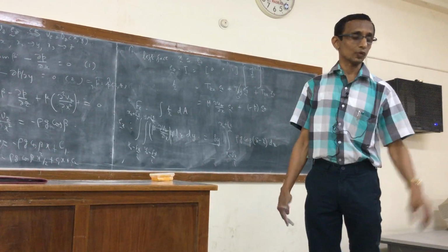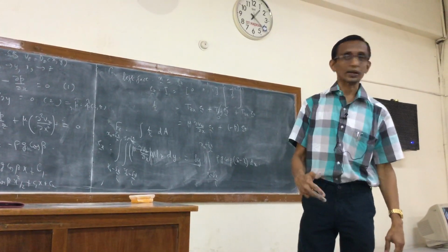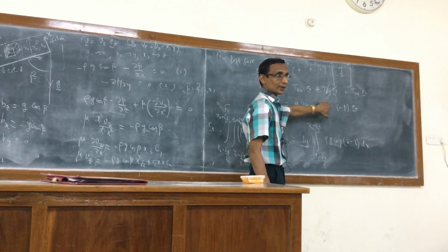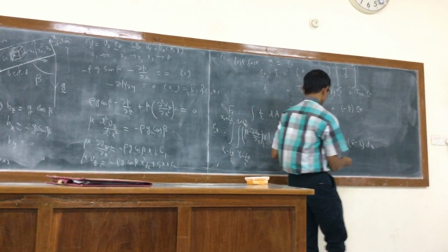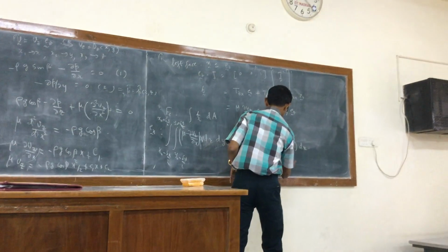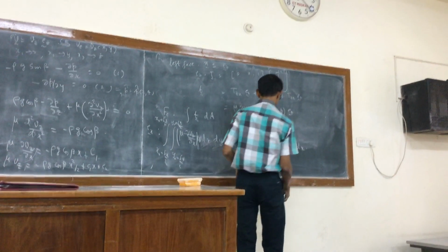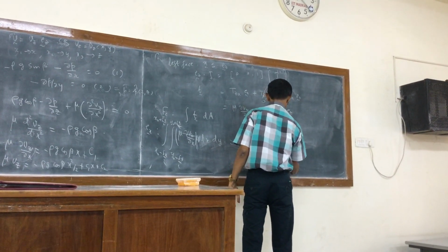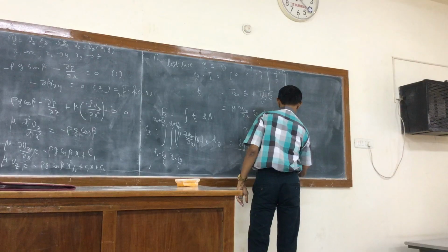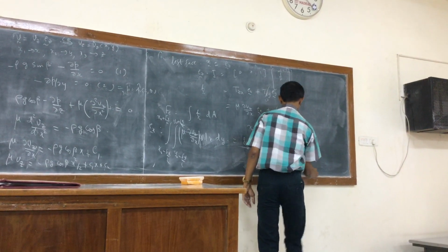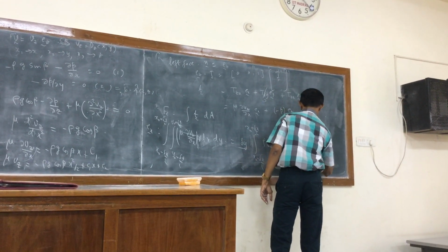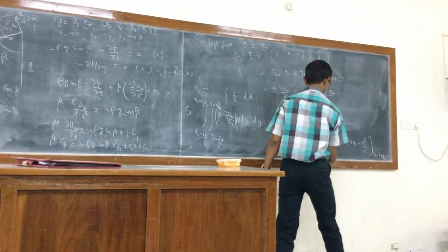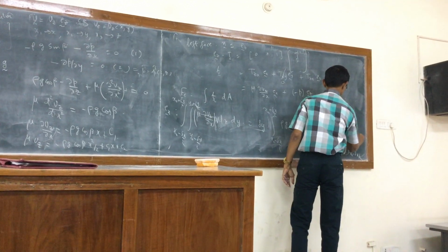This is the contact force that you would get for the left face. Only part of the contact force. This is the normal part that we have to calculate. We have to put all of these together, so this can be easily integrated. I'll make you do the integration. So this would be rho g cos beta delta x minus x squared by 2, and it would run from x0 minus delta x by 2 to x0 plus delta x by 2.